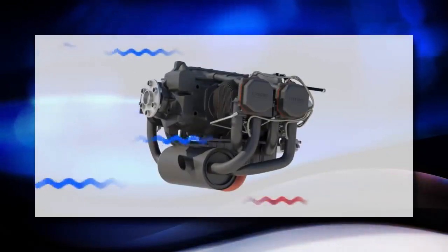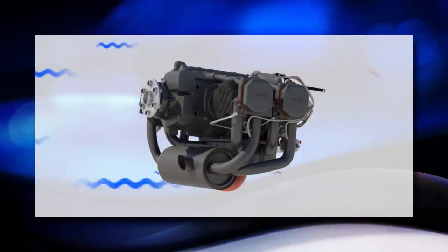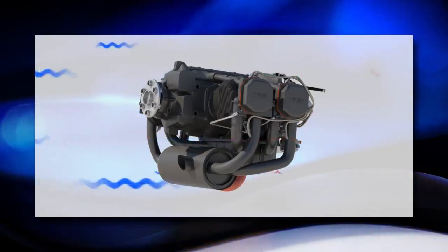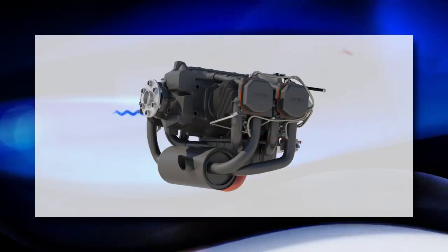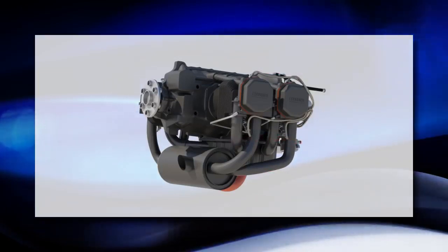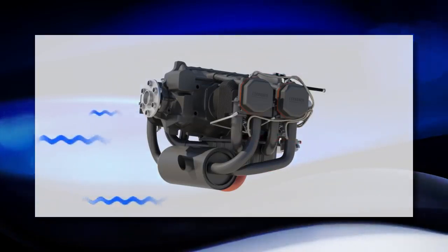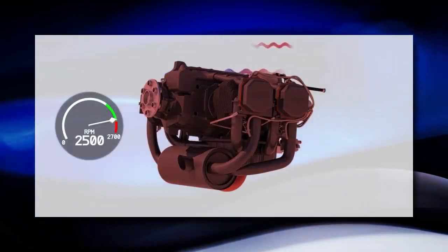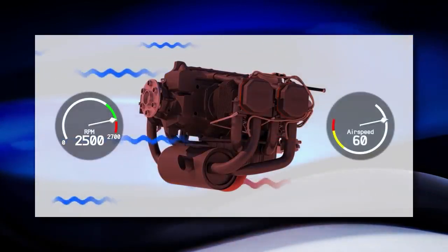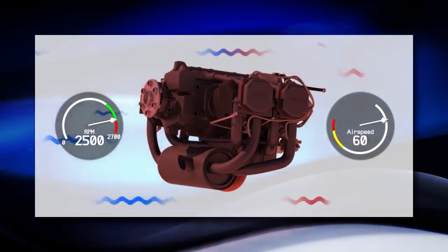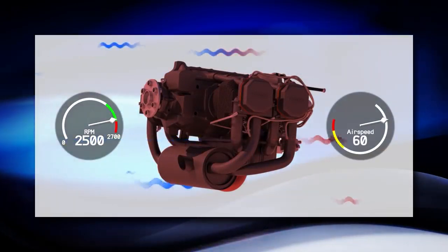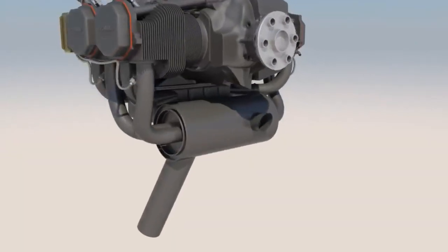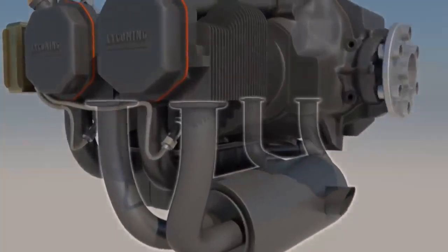We also use air to cool our engines as the airplane flies through the air. Outside air flows through inlets, usually found on the front of the airplane, like the Cessna 172. This outside air is colder than the engine, so as the air flows over the engine, it cools it in the same manner that the oil cools the engine. This method of cooling can be severely restricted, however, when the airplane is running at high power and at very low speed, such as when climbing. Airflow is minimized, causing higher temperatures. The last step in the 4-stroke cycle is the exhaust.